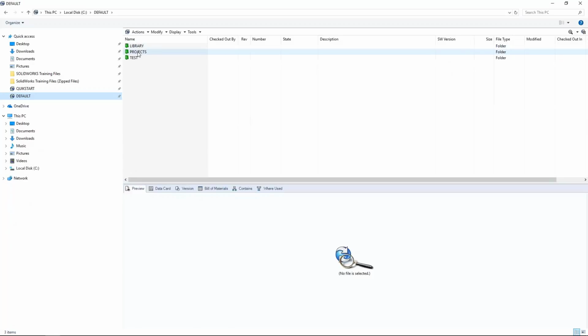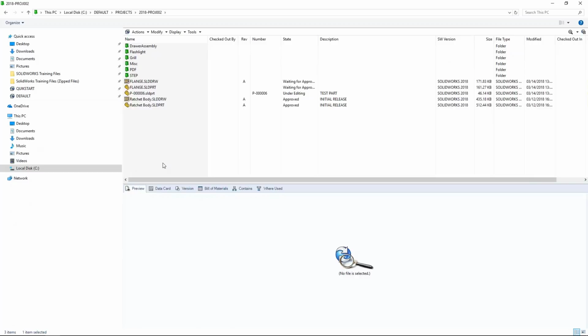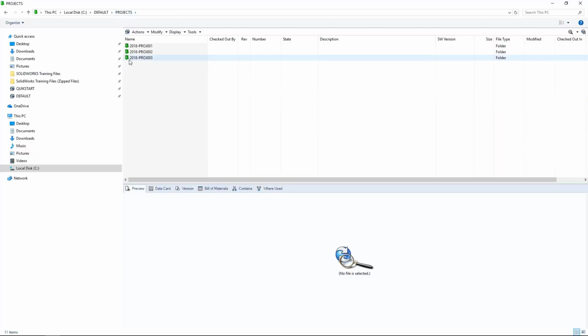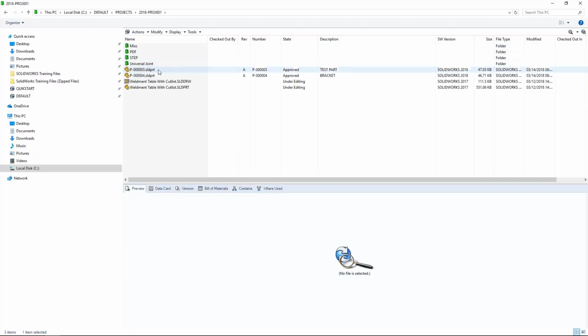All right, and let me shut all this stuff down, because again, Mr. Manager doesn't have SOLIDWORKS. I'm now in the system, and again, apologies for my machine being so slow, but the system can be set up so that the manager gets a notification of that transition from work in progress to pending approval. The notification is available both in standard and professional. However, in professional, you can actually hook it into your existing email system, be it Outlook or Gmail or something like that.